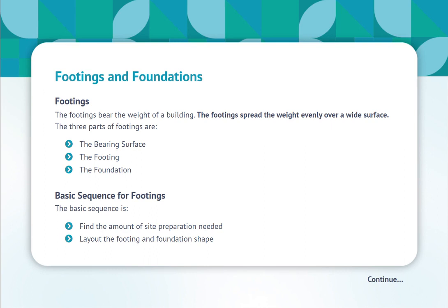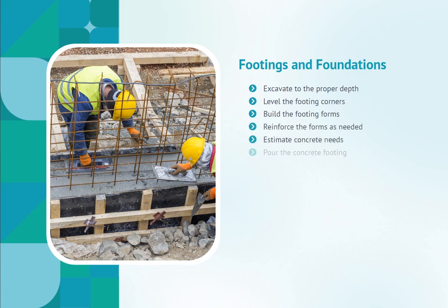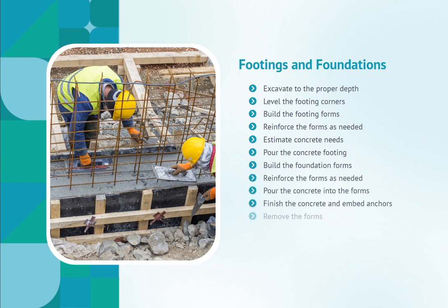Lay out the footing and foundation shape. Excavate to the proper depth. Level the footing corners. Build the footing forms. Reinforce the forms as needed. Estimate concrete needs. Pour the concrete footing.